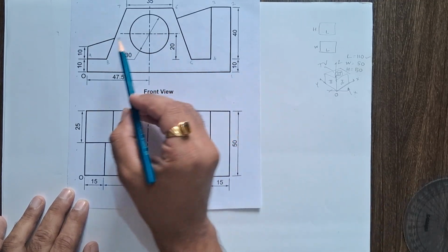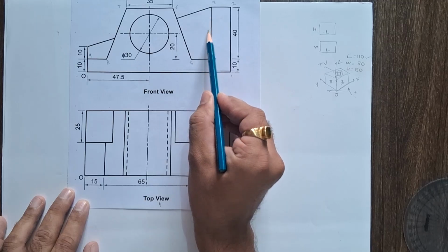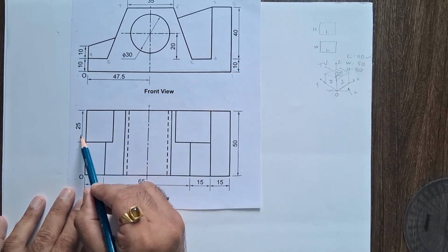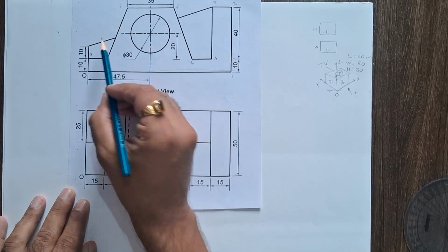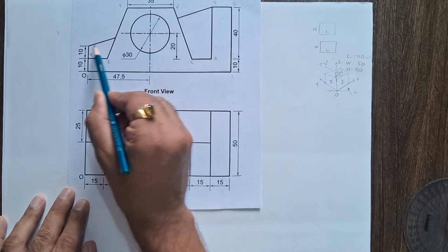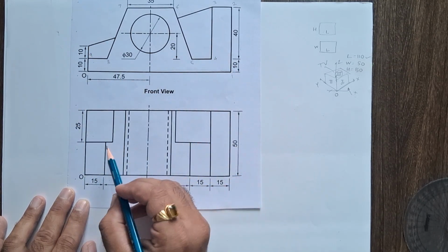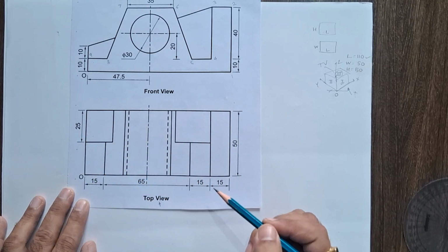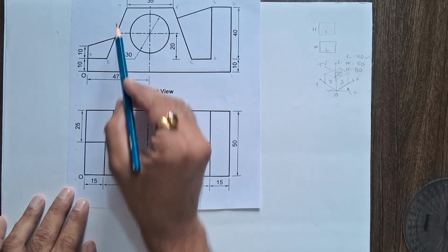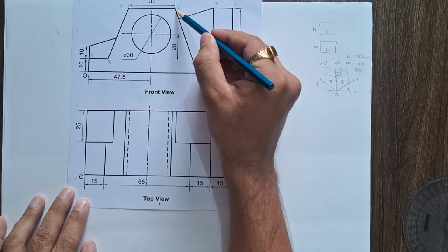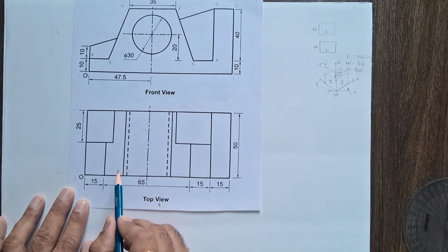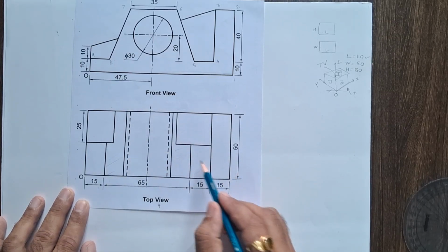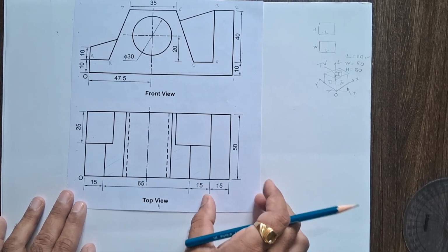Now on the back side there is a rib or just a triangular part. The thickness of that triangular part is 25 mm. This part which you see, of triangular shape, its position is back side of this object and thickness is 25 mm. And this surface is the slant surface. You can see this slant surface position is here. This is a slant surface. Now see the solution for this problem.